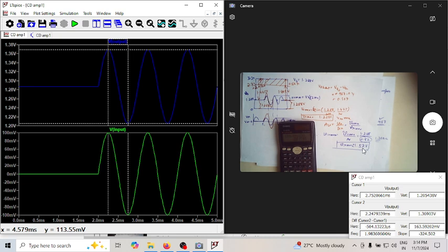This input maximum, we found it as 1.57. How to verify that: you can see now I have a space. This is at 1.2, this is at 1.36. You have a lot of space till it goes to the linear region, and a lot of space till it reaches 0. So now let us increase the amplitude up to less than 1.57.